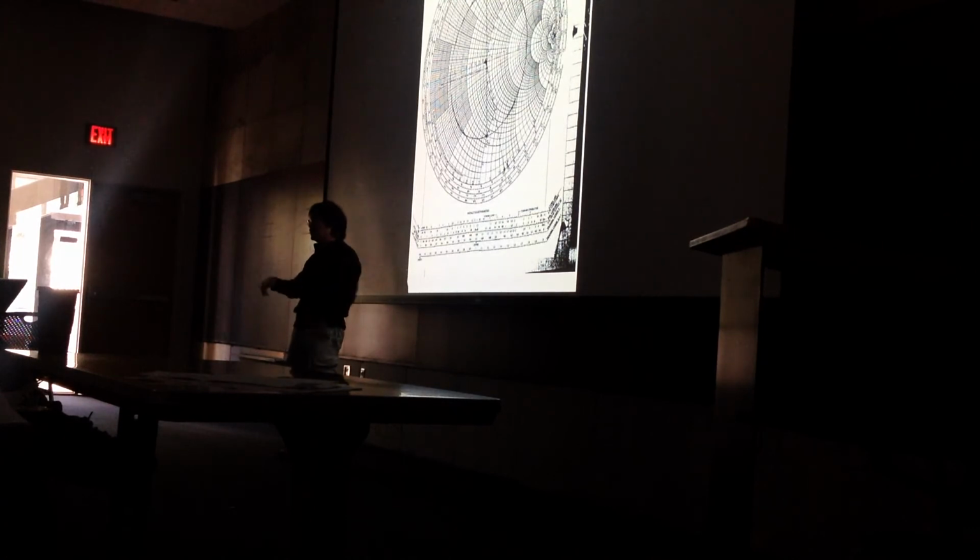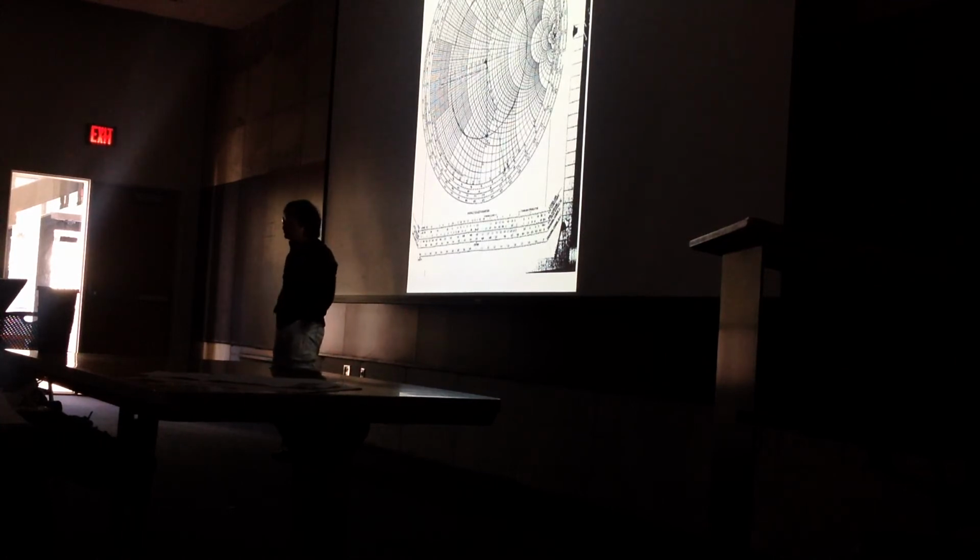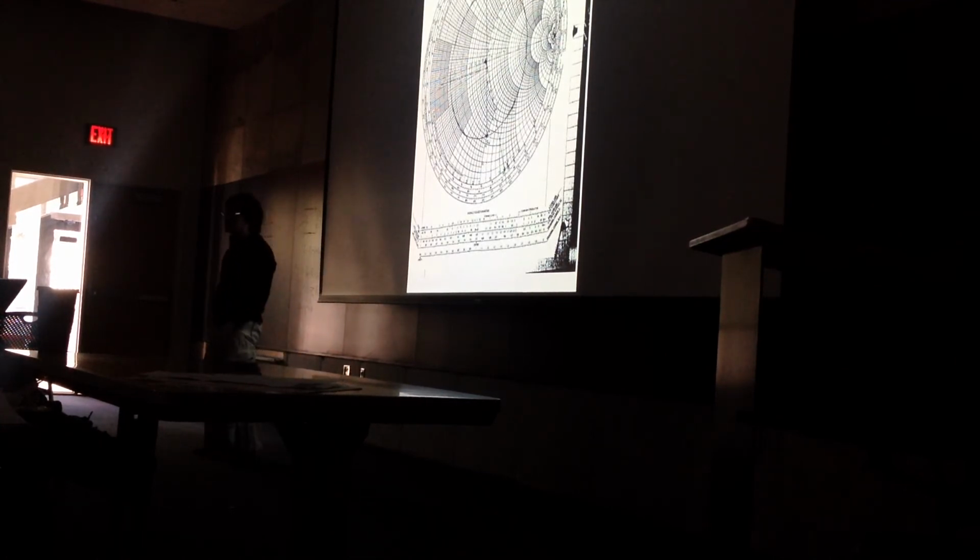Two ways to look at it. One, that's the intercept of R equal to 0 and X equal to 0. Two, when ZL is equal to 0, what is your reflection coefficient? Remember, gamma is equal to ZL minus Z0 divided by ZL plus Z0. So if ZL is equal to 0, what do you get? Minus 1. That's the reason it's on the left. On the right, that's 1. On the left is minus 1.